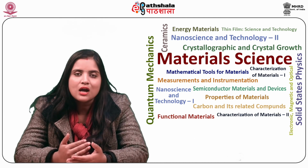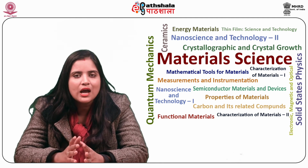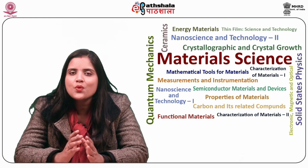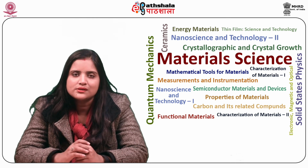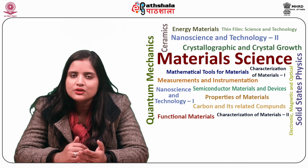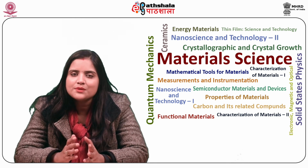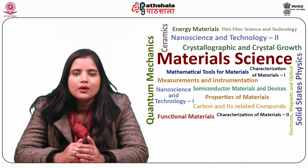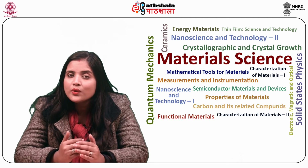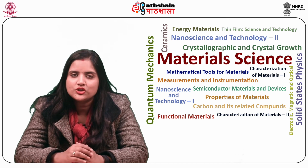Lately, semiconducting nanobelts or nanoribbons of binary oxides have been fabricated via evaporation and subsequent condensation of the precursors. Examples include the nanobelts of zinc oxide, In2O3 indium oxide, gallium oxide, cadmium oxide, etc. Precursor was used in powdered form and was vaporized inside a tubular furnace at high temperatures.